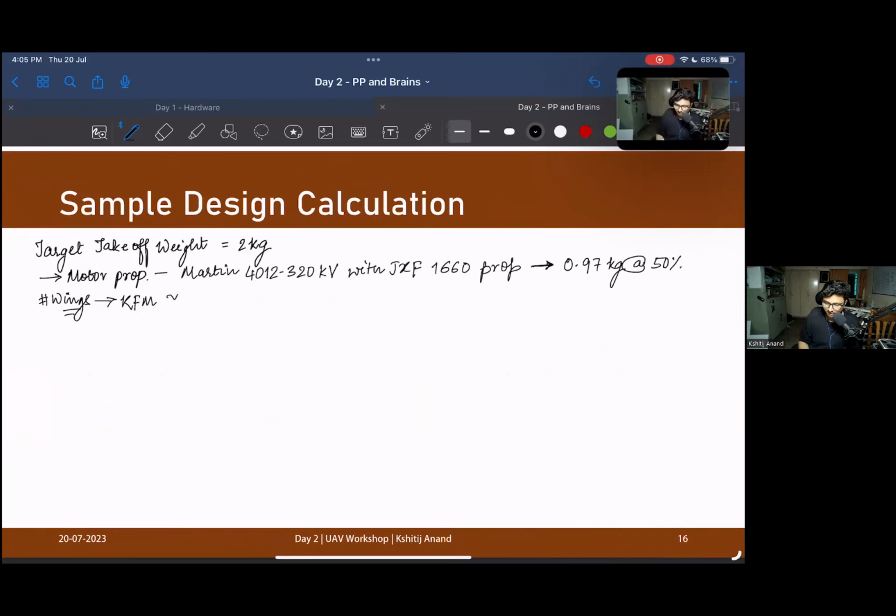So you can take your initial lift coefficient at zero angle of attack. Your lift coefficient should be somewhere around 0.5 to 0.8. We will still take it on the lower side. For our calculation purposes, we will take that CL is roughly equal to 0.6 at 0 AOA. Okay. So now what is the lift? The lift is going to be half rho V square C B CL.